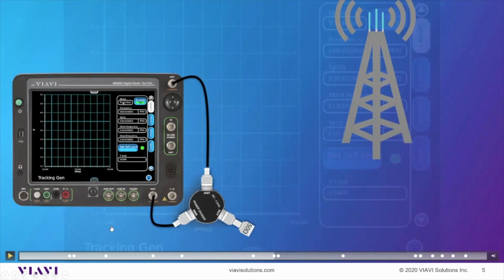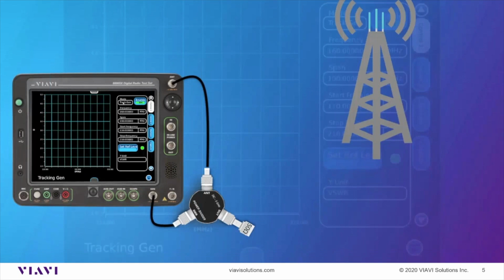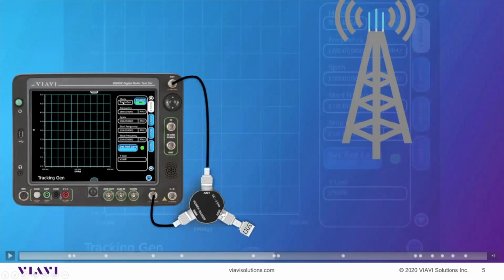So what we're doing here is I've taken the return loss bridge off of the service monitor. I've put the power divider on. These two items are in that kit that we talked about early in our presentation. And on this one, we don't have an open out here on our device under test port. We do have a 50 ohm load out here, but it's hooked up the same.